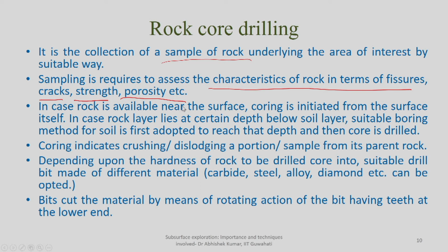That will define two things. One is the characteristic of the medium in relevance to the kind of foundation you are designing for the project you are targeting. And second, this porosity, strength and cracks will also define, particularly in the case of tunnels, how suitable the site is for that particular kind of project.